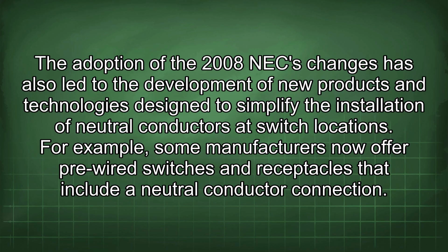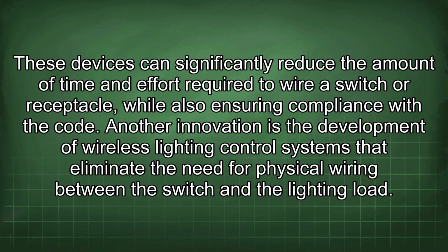The adoption of the 2008 NEC changes has also led to the development of new products and technologies designed to simplify the installation of neutral conductors at switch locations. For example, some manufacturers now offer pre-wired switches and receptacles that include a neutral conductor connection. These devices can significantly reduce the amount of time and effort required to wire a switch or receptacle, while also ensuring compliance with the code.